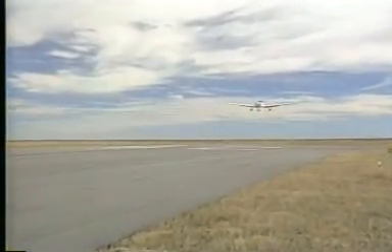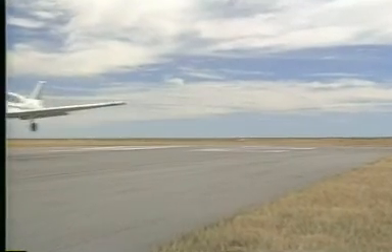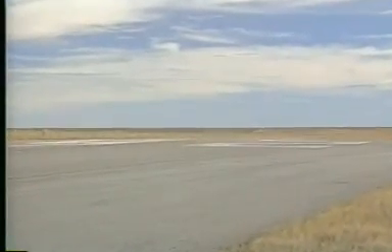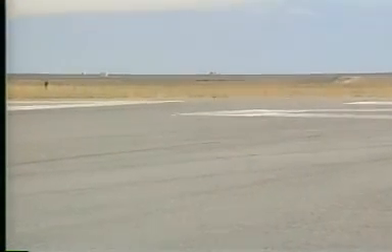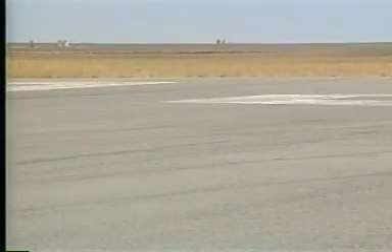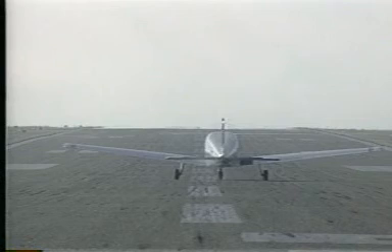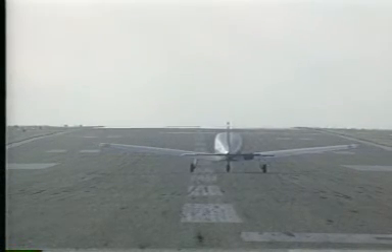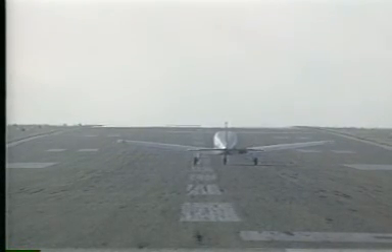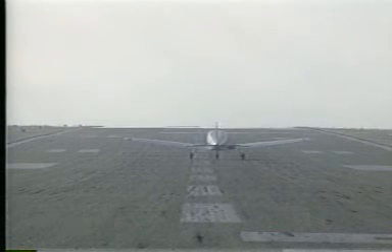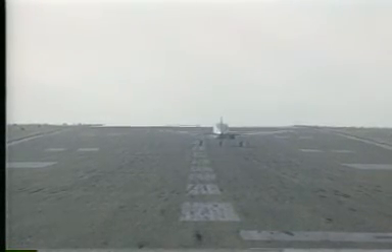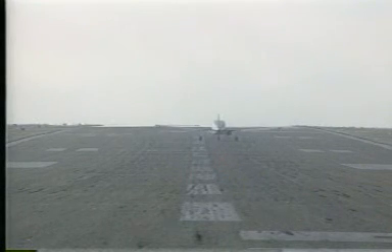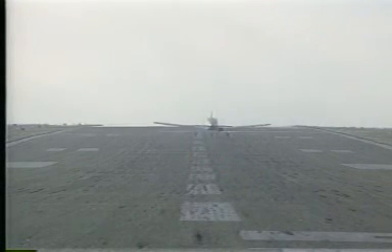Aircraft performance can also be influenced by the runway itself. Many runways slope from one end to the other. You need to consider the gradient when determining takeoff and landing distances. For example, if you land uphill, the airplane will decelerate faster than normal, which will decrease the landing roll distance. On the other hand, departing uphill will lengthen the takeoff roll since it takes longer to accelerate to liftoff speed.